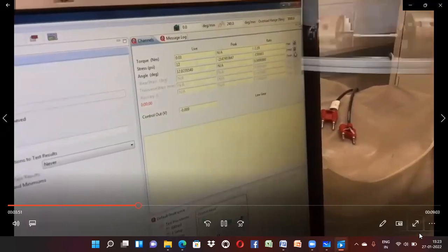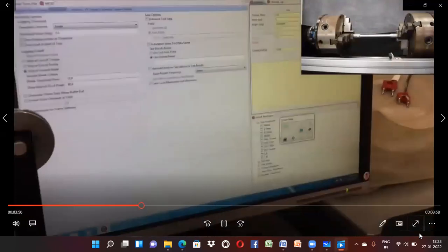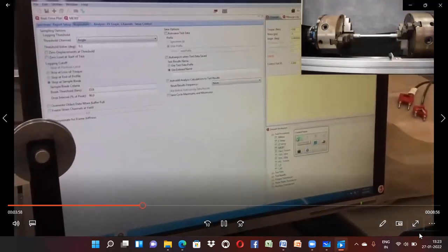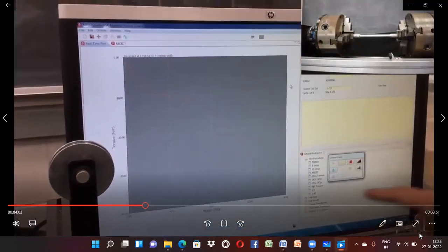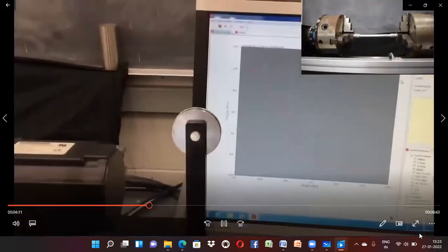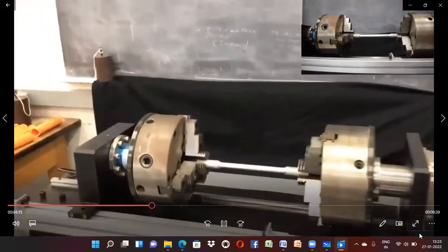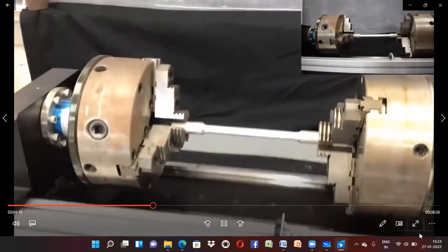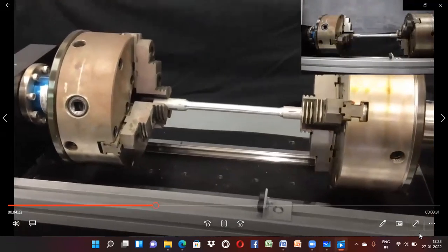Okay, so he goes over here and just zeros the two channels there. You don't have to right click it. There's actually a little button for zeroing. And then he clicks play and it begins. And what's going on? This makes no sense. We've got angle and torque, right? Angle on the horizontal axis, torque on the vertical axis, but the torque is dropping. Yeah, so it turns out that with this one, as we're looking into the chuck, a counterclockwise torque is considered negative in this case, right? Not a big deal. We can handle that.